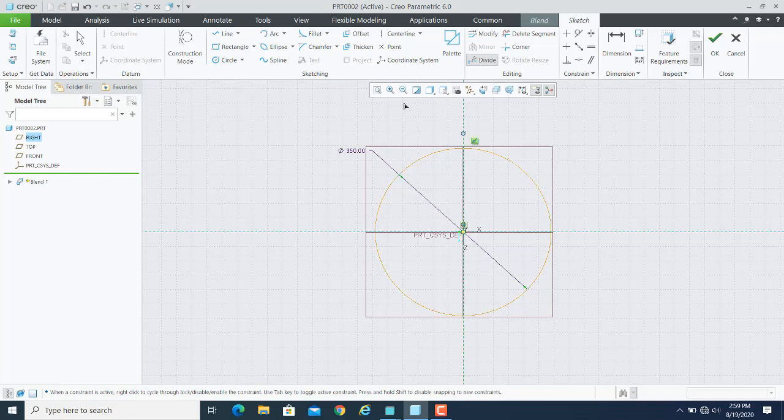So I can take any point as my dividing point. As we need 4 points, I will start with the quadrants. So this is, let us say, my first dividing point. This is the second dividing point. This is the third, and this one is the next one. So I have divided this circle into 4 segments. Right now we do not have a circle, but we do have 4 arcs. So we have 4 points, and then those 4 points can be joined with a square or rectangle.